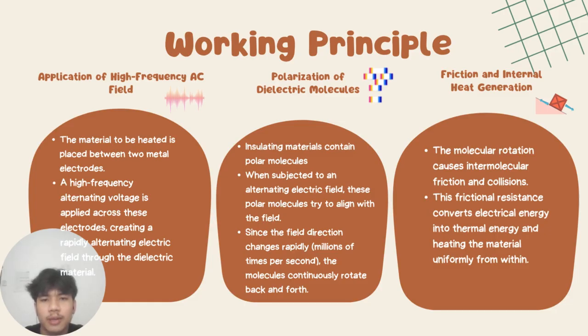Now I would like to explain the working principle. First is application of the high frequency AC field. The material to be heated is placed between two metal electrodes. A high frequency alternating voltage is applied across these electrodes, creating a rapidly alternating electric field through the dielectric material.